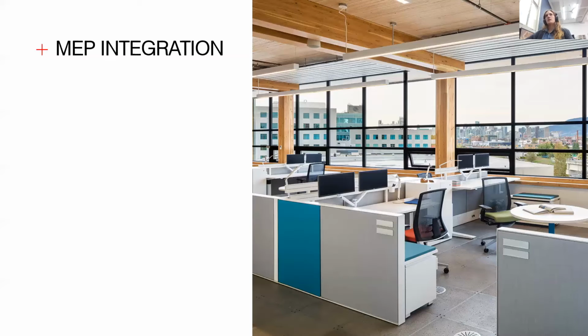Here you can see there's 2 girders which are offset from each other, which leaves a space in between beams where you can tuck in some electrical, mechanical routing. There are other strategies as well, but this becomes a key point.